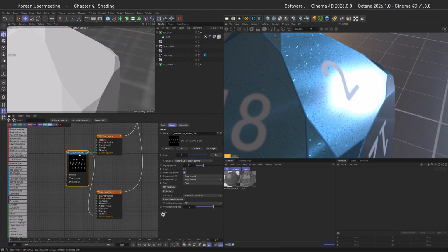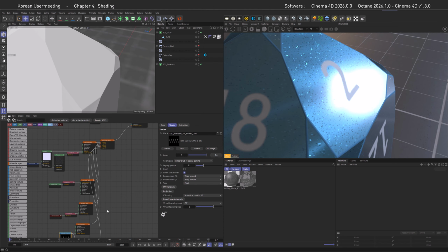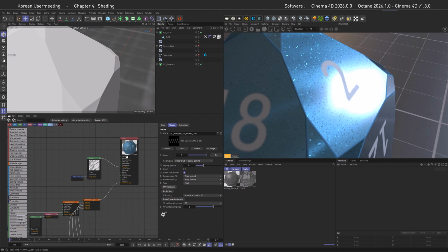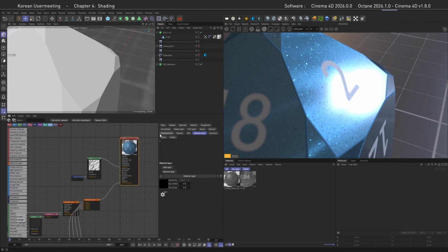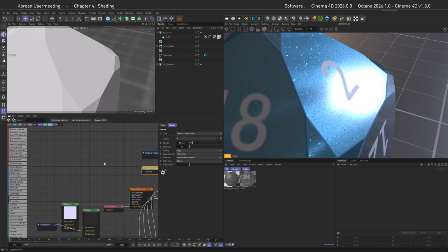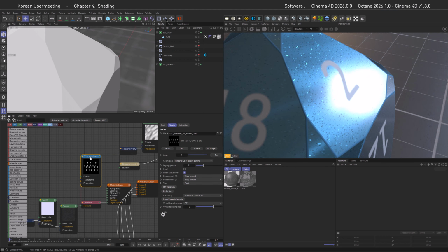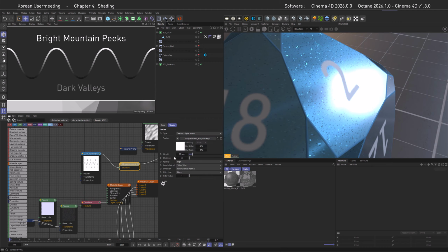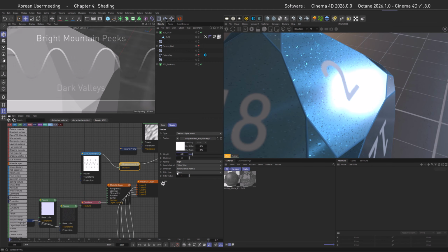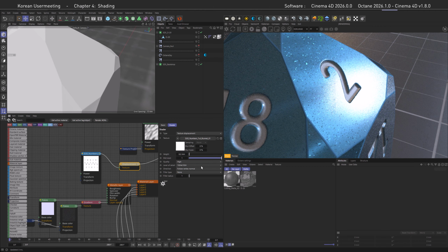Now, as promised, no more layers, but to get the shader home, we need one more thing, and this is displacement. Let's create a displacement node and also bring back in our numbers. What I want to do with them is actually invert them, because light is always hilltop and black is the valley. Before it refreshes, let's actually go with a smaller value like 0.2 and then also adjust the mid-level so the actual surface of the object is not altered.